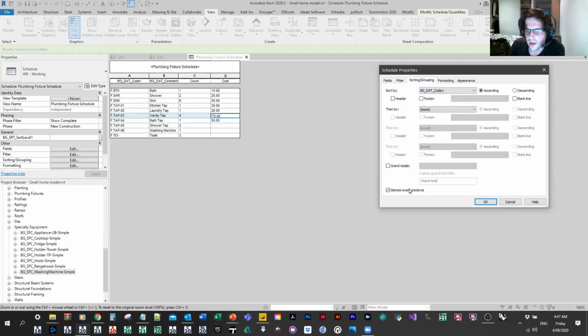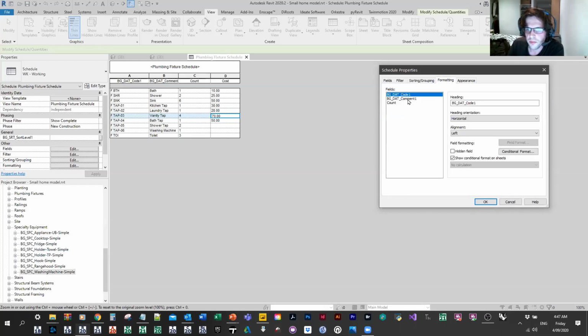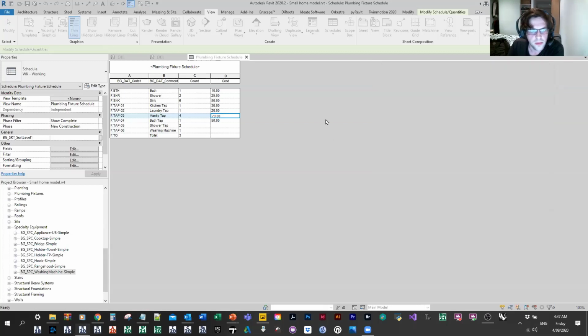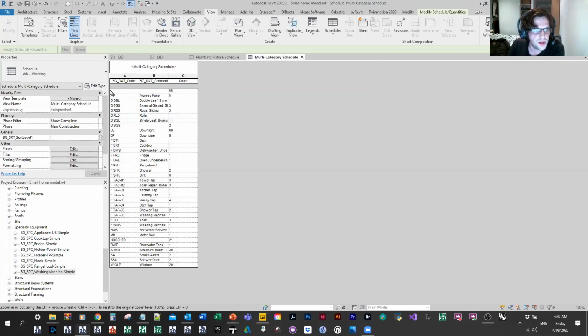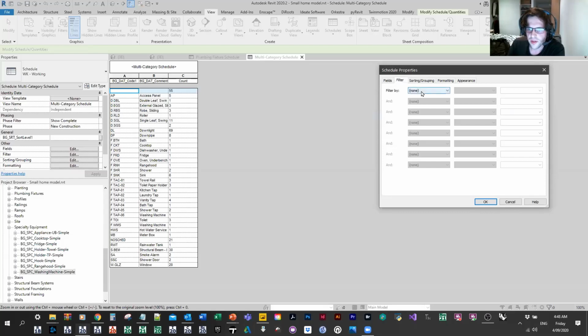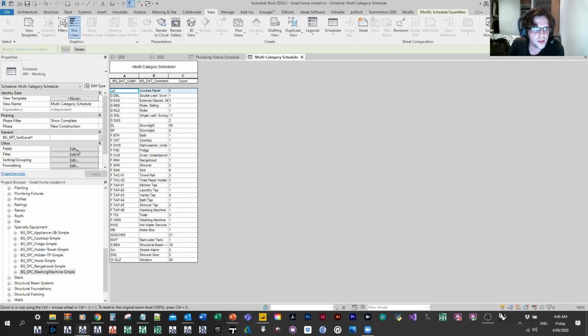I'll just sort by code, and I'm going to turn off that itemized parameter again, so that we're just going straight into rows by code. And at that point, we probably don't really need to change anything. Now, you get a few things, like you'll get things that don't have codes. These typically are things that aren't intended to report. There are various ways of managing these out. I find depending on the schedule that you're working in, the method is different. Sometimes one method that does work is just to say code has a value. I know sometimes this works. Yeah, so in that case, it works.